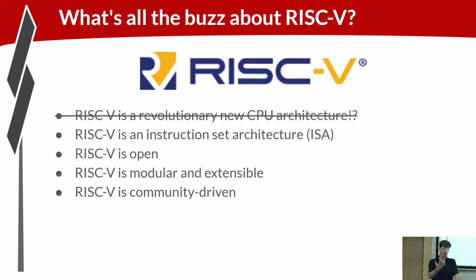So if you implement a RISC-V CPU without support for the M extension and the CPU encounters that instruction, it might take a trap to a trap handler that's going to do the software emulation of that instruction and then return execution to your code. So it'll function correctly. It won't perform those operations natively. It won't be performant for them, but it'll work. And so by layering on all these architectural extensions, you can implement cores with different characteristics that are appropriate in different circumstances.